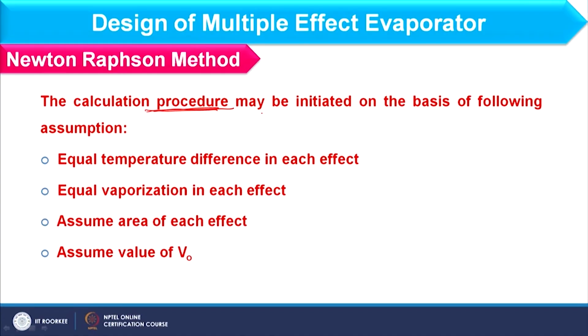So, the calculation procedure which you can consider to solve set of nonlinear equation using Newton-Raphson method, you have to take some assumptions, and these assumptions are basically equal temperature difference in each effect.